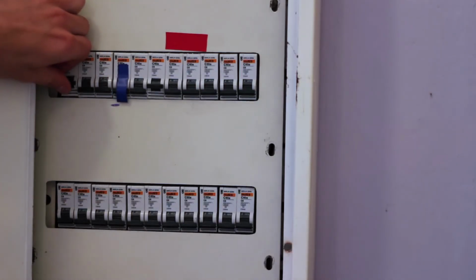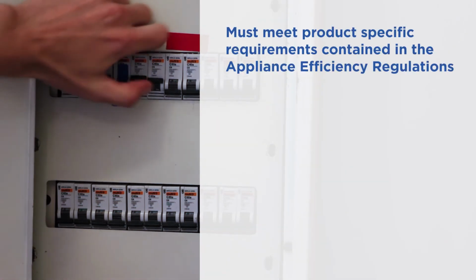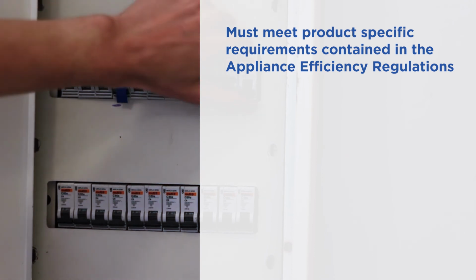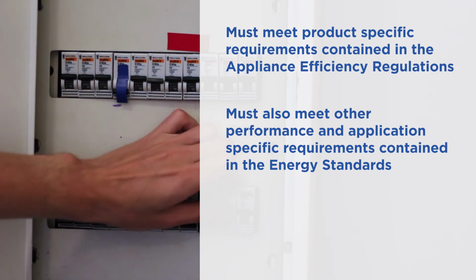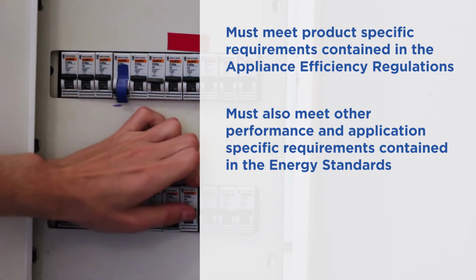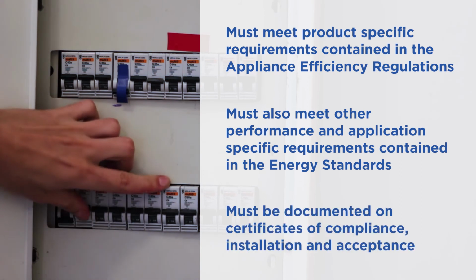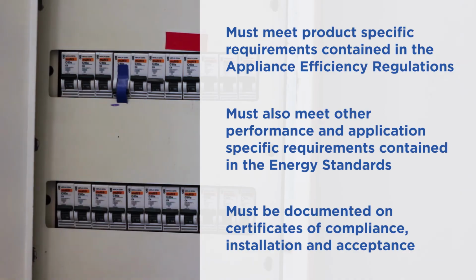Before we end this module, let's review what we've learned. Lighting control products installed in California buildings must meet product-specific requirements contained in the appliance efficiency regulations and other performance and application-specific requirements contained in the energy efficiency standards. Lighting controls installed to comply with the energy standards must be documented on certificates of compliance, installation, and acceptance.